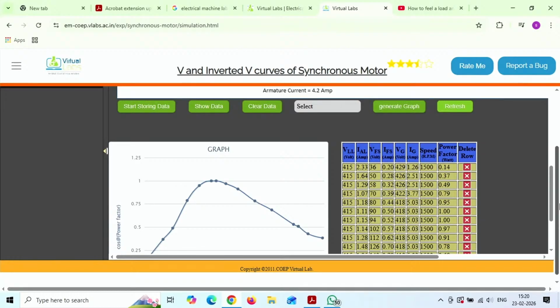We have the symmetrical components, out of which we can see the parameters, say currents: positive sequence, negative sequence and zero sequence. Positive sequence means under balanced conditions, the currents flowing in the uniform rotation direction, ABC or RYB sequence, as observed during normal conditions. If a short circuit happens, how much reactance is the alternator providing?